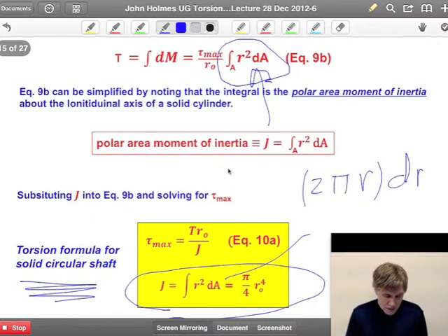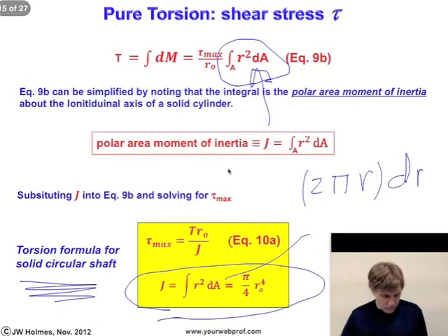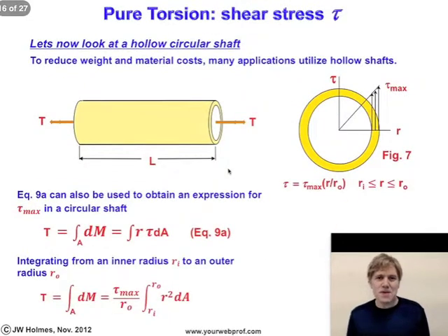So for a solid circular shaft under torsion, we're there, but life's not so easy, because many shafts are tubular or hollow shafts. There's a reason for that. It has to do with things such as resonant frequency, efficient use of material, and low mass. You typically want a low mass shaft.